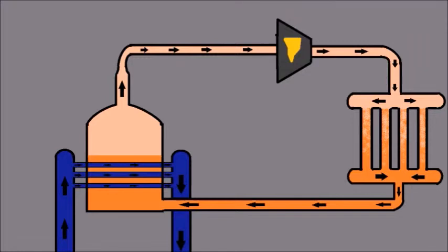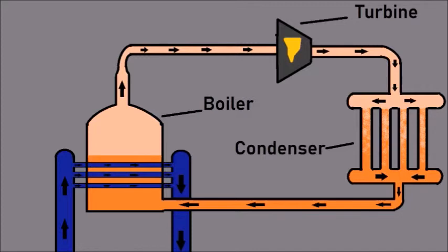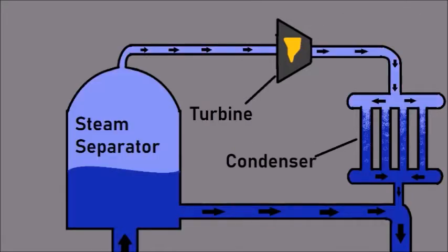In this case, the hot water can be piped through a different fluid, and that different fluid can boil and run a turbine. These types of geothermal power plants can take advantage of lower temperatures because they don't have to be hot enough to create high steam pressure.